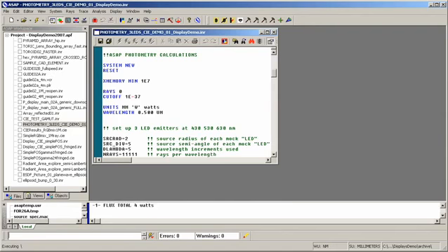I'm going to run this with a fairly small number of rays first. Basically, I'm running 81 wavelengths per LED and 11,000 rays per wavelength. So that is a modest number of rays for a colorimetric analysis. And I'll show you that result, and then we'll get the result for a great number of rays so that you can see how color noise improves as you use an appropriate number of rays in the analysis.